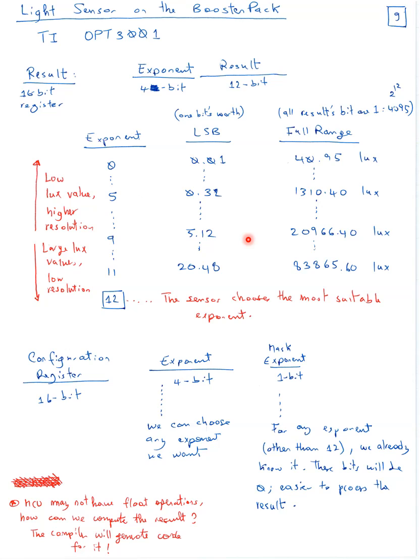the experiment in lab 9, we're supposed to measure the lux values in a classroom, and that, I believe, is about 1,000 lux. So we would need to set it somewhere in the exponent between 5 and 9. We can go a bit more than 1,000. So you can test, like, if you flash your cell phone's LED on it, you can go up to maybe 8,000 lux, for example.